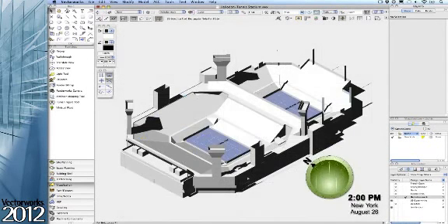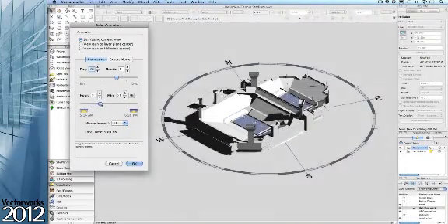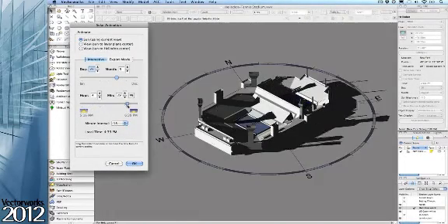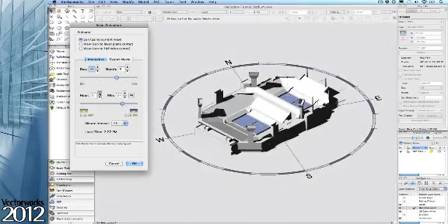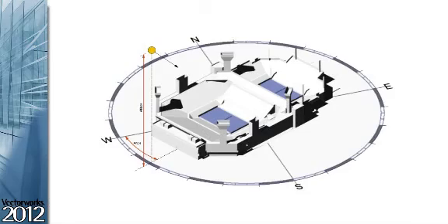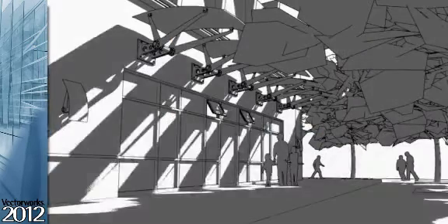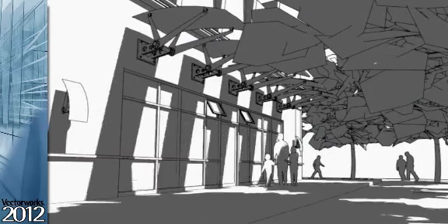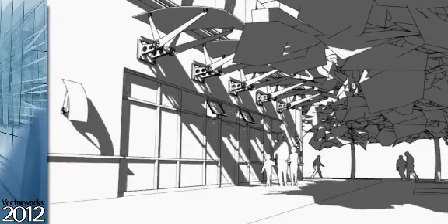These two dialogues represent the control center for your solar animations. Our unique solar marker is a hybrid object containing the light source, and it displays information when in top plan view. Here it's easy to dynamically control the path of the sun that you've defined just by manipulating the slider control. Setting up and running solar animations is a snap, and by naming up to 4 walls in the document, the shadow angle calculator will help you discover the altitude and horizontal shadow angle. This is the data you'll need to explore the effectiveness and design shading systems.